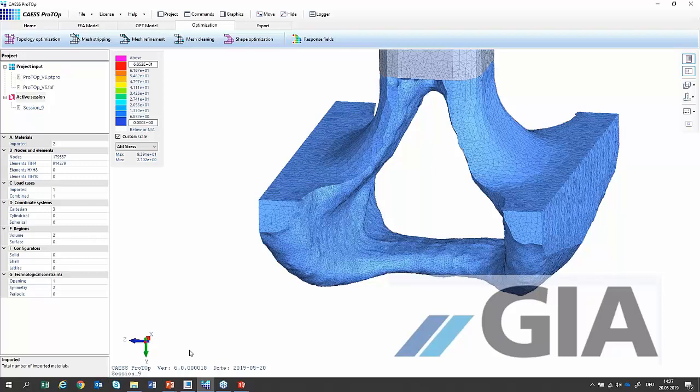When you have the topology optimized shape, you get a nice surface. But I would say you cannot use this surface for a casted part, just as we cannot use the raw surface for a really casted part. At the end of the day, you have to recreate a very precise surface with standard features in the CAD system. So the first directly copied surface from topology optimization is not suitable for a perfect construction.